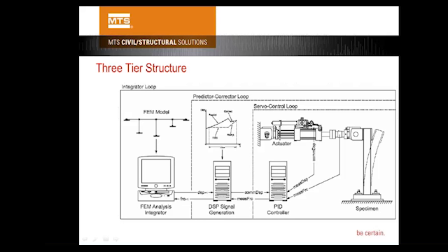So in between, this predictor corrector model is running, so it keeps the real time. At each closed loop rate moment, each clock tick, the test needs a command, so it watches the analysis model. If the analysis model at this moment is not solved, then it predicts a command, sends it to the actuator and runs, and keeps going, predicting until the model is solved for this moment.